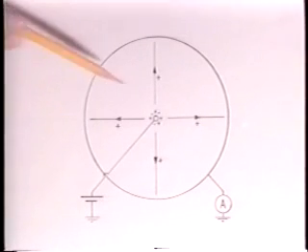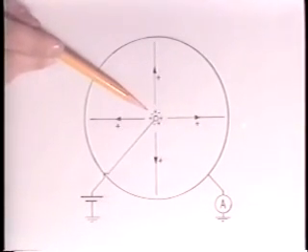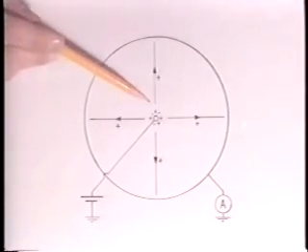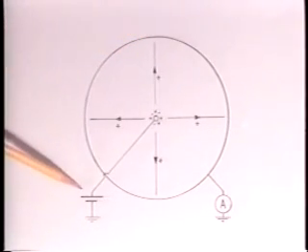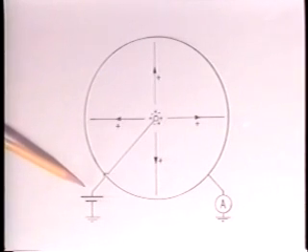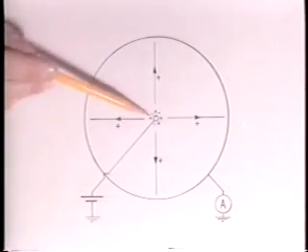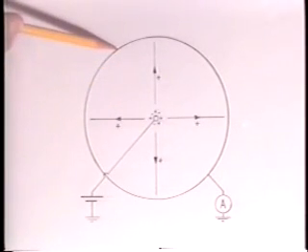Pairs of ions generated by the corona discharge are separated by the electric field. Some of the positive ones follow the field lines to the outer cylinder. Thus, as we raise the voltage and hear the discharge start, there should be an onset of current passing from the inner wire to the outer cylinder.